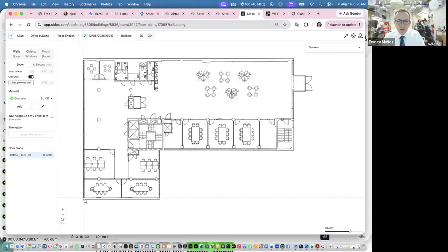We're in walls and then one click. And we talked about it yesterday. If I just move the mouse to draw a wall, it goes 90 degrees, 45, 0 degrees. So it has that 45-degree jump. To release that one, you hold the control key. Then you can just go wherever you want it to go. Okay, it removes that 45-degree jump.